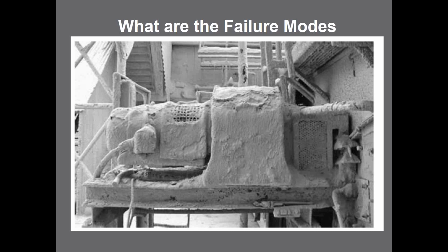The PM task said, check the gearbox on this piece of equipment. Well, how would you put oil in that? What are the failure modes around the electric motor we talked about when it's covered with cement dust? How would you effectively add oil to that gearbox or check oil in that gearbox without getting anything in it? It looks like the maintenance person probably wiped the coupling guard off to see if the coupling was actually turning. But again, what is the PM? Why are we doing it? Why is that grease gun laying underneath there?